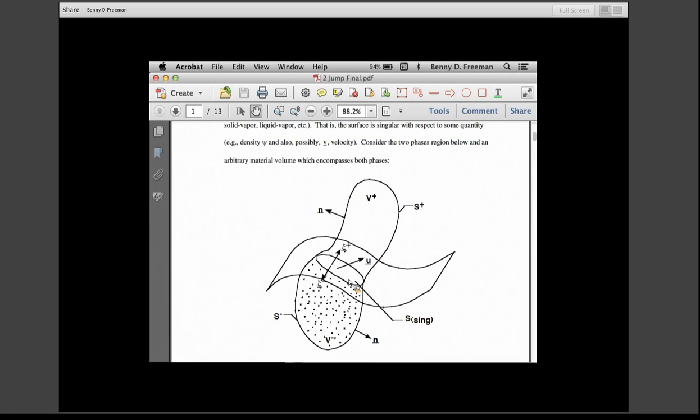So for example, we're going to come back and have a closer look at the Stefan tube problem. And in that problem, you have a liquid-gas interface, if you remember, and you have liquid evaporating from that liquid phase into the gas phase. And so that must mean rigorously, if no liquid's being added to that system, that as the liquid evaporates, that liquid level moves down in the Stefan tube. In fact, that was one of the ways that we track and measure the diffusion coefficients in the gas phase, watching that liquid level go down.